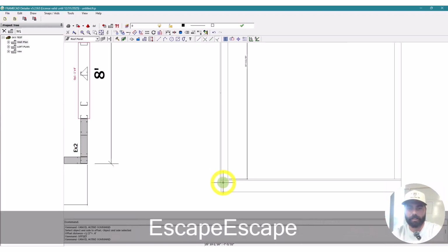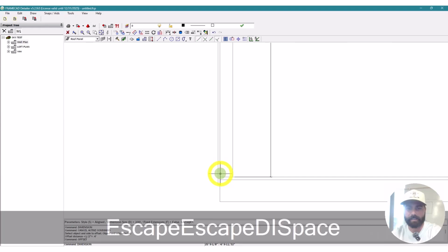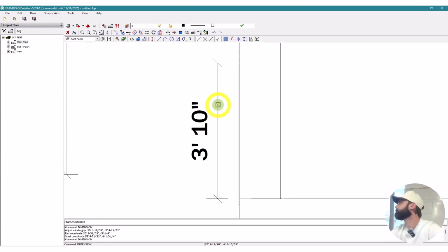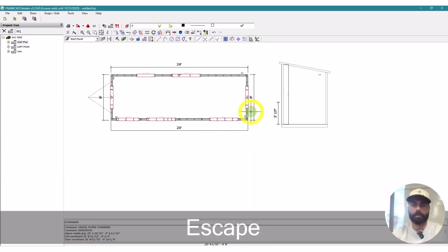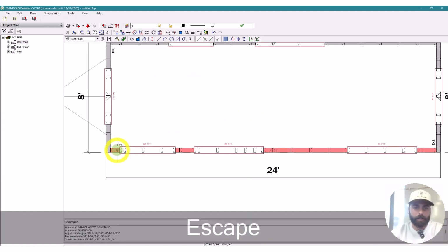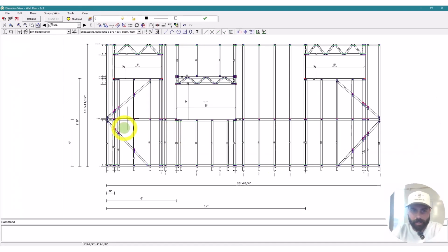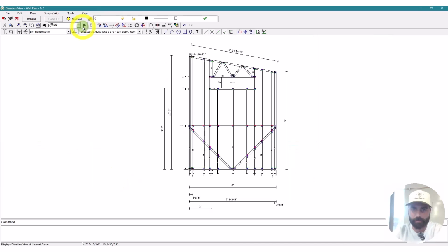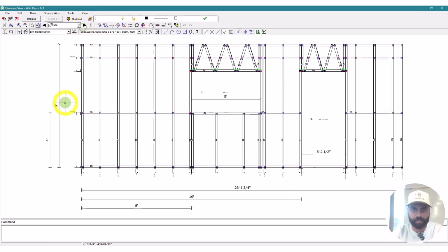So this one we went ahead and fixed. This should be 16-inch centers. We got our bracing in, 16-inch centers. This is 16, but we didn't account for that half step. So we're going to go ahead into our stud references again. We're going to edit this to be -3 5/8 inches. Okay.